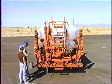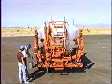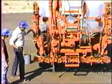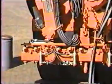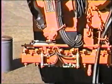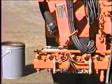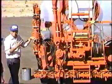Also, down on the swing joint is another butterfly valve on an air cylinder, on each swing joint, here and on the other side. They're tied to the same solenoid control valve as the main equalizer valve. These are auxiliary equalizer valves, or swing joint equalizer valves. When we turn that master switch on, all three equalizer valves snap open.